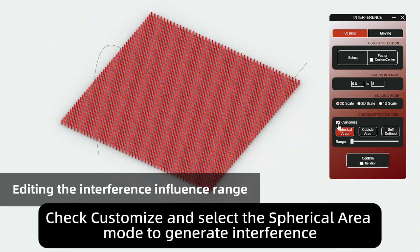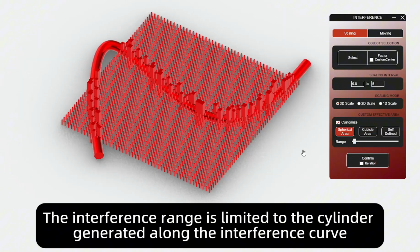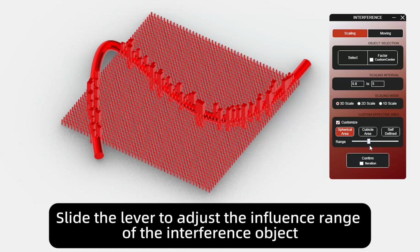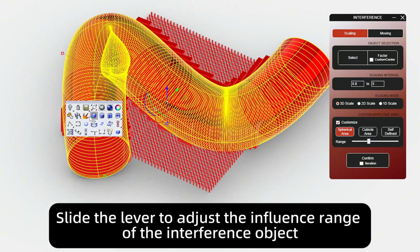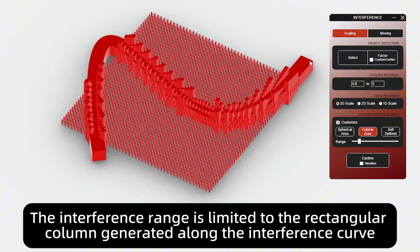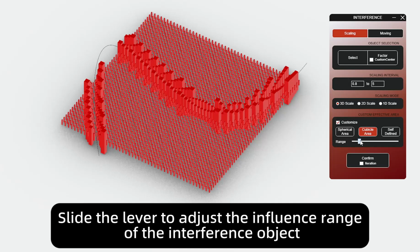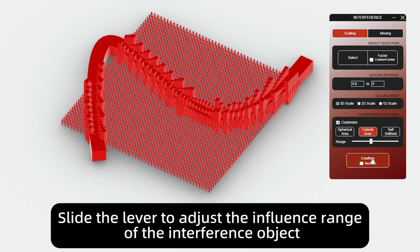Check Customize and select the spherical area mode to generate interference. The interference range is limited to the cylinder generated along the interference curve. Slide the lever to adjust the influence range of the interference object. Switch to the cubical area mode and generate interference. The interference range is limited to the rectangular column generated along the interference curve. Slide the lever to adjust the influence range of the interference object.